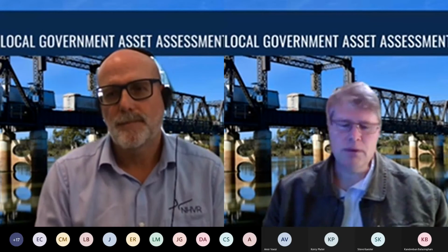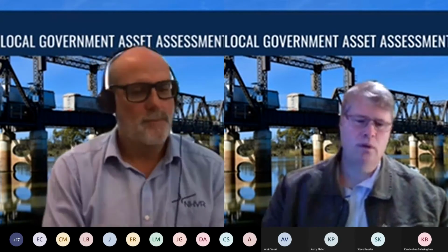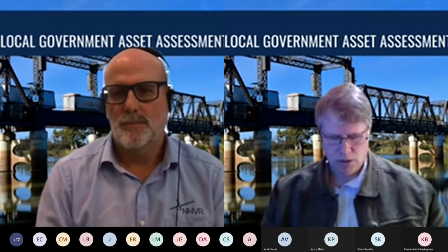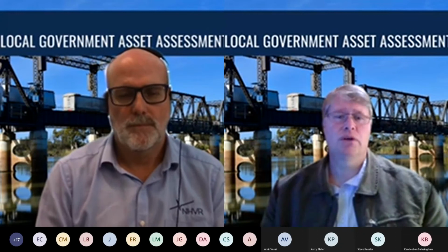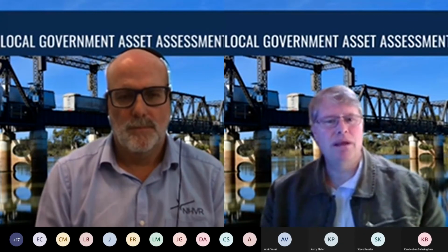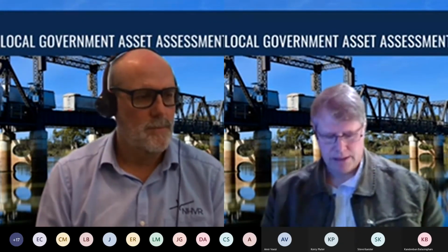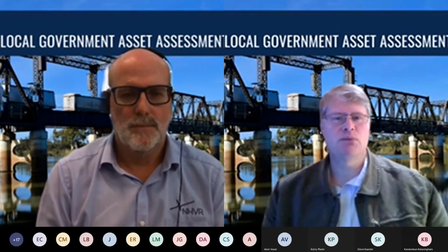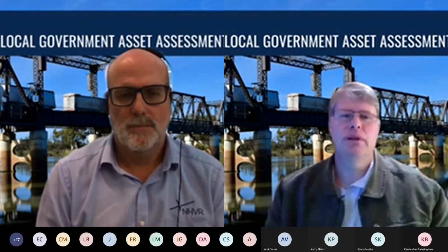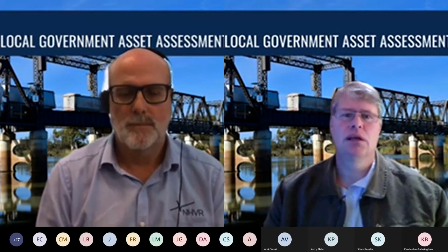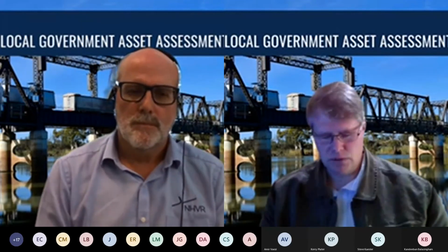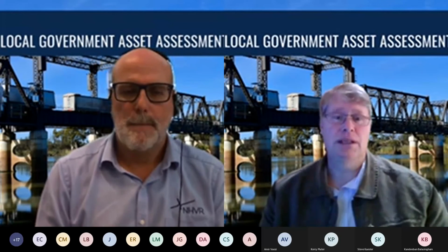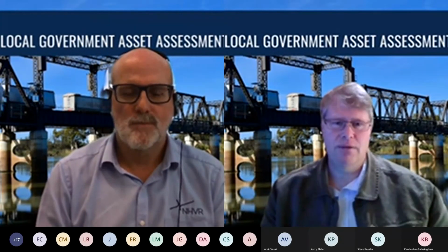Yeah, look, what's tricky about that is that if a report has already been done, and it specifically excludes the substructure, then you, as someone trying to use the information, need to make an assessment on whether the substructure matters or not. You need to look at what sort of makeup the substructure is. Is it blade piers? Are there cantilevers with narrow headstocks? All these things could really start to influence whether or not you can use the results. Unfortunately, in that situation, the bird's already flown the coop, so to speak.